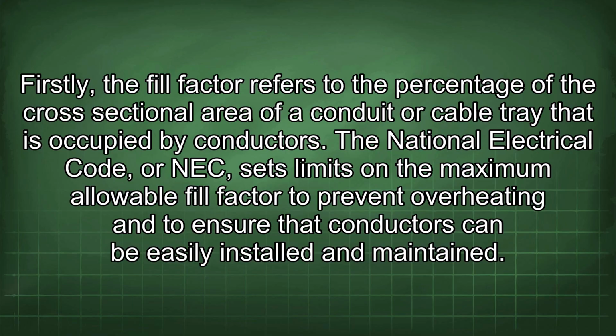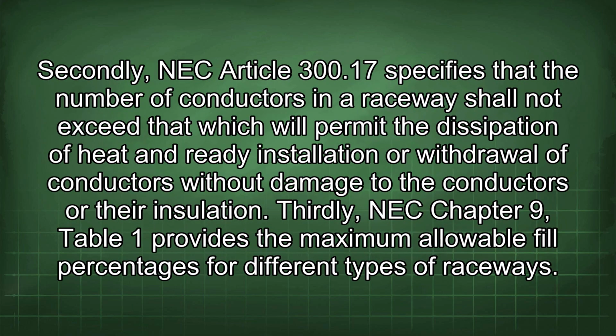cable tray that is occupied by conductors. The National Electrical Code, or NEC, sets limits on the maximum allowable fill factor to prevent overheating and to ensure that conductors can be easily installed and maintained. Secondly, NEC Article 300.17 specifies that the number of conductors in a raceway shall not exceed that which will permit the dissipation of heat and ready installation or withdrawal of conductors without damage to the conductors or their insulation.